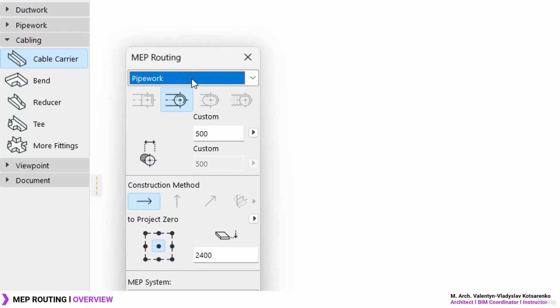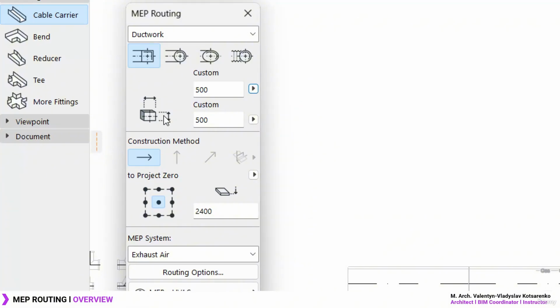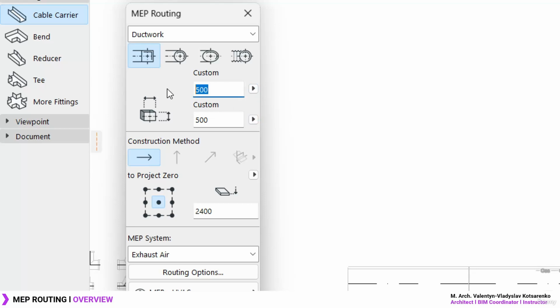And once you're done, you can go ahead. For example, let's activate ductwork, set the profile you want to use, and then start adjusting the measurements. You got the standardized measurements you can specify in map preferences. In this case, it's going to be for two different dimensions, one which is the width and one which is the height. Right over here you can specify width and height, or you can input a custom measurement for your profile. If it's circular or an ellipse, well, in ellipse you got two measurements, in circular you got only one, and in the flexible one you also got only one.